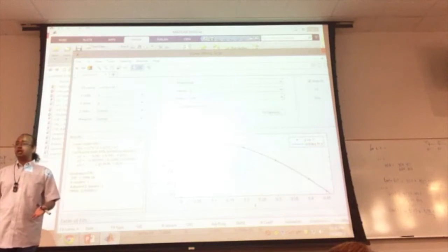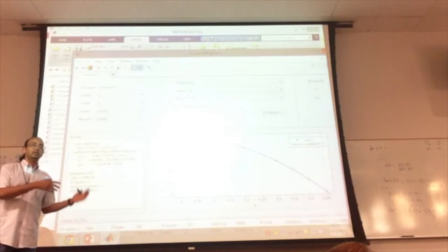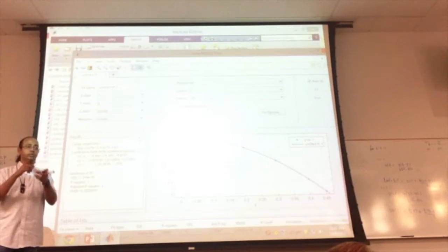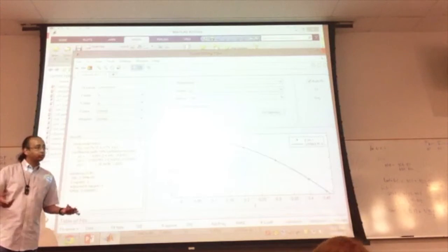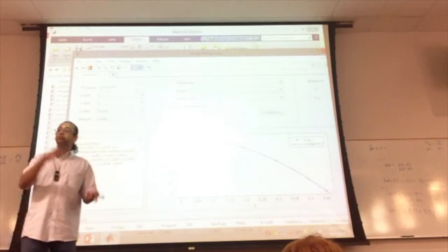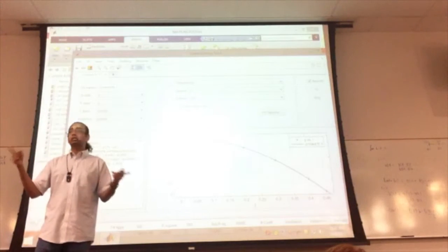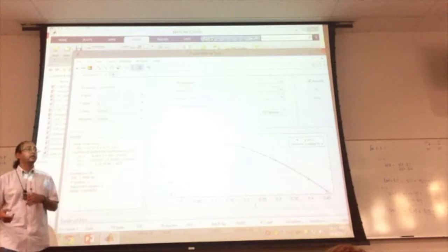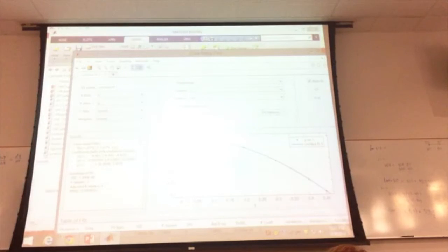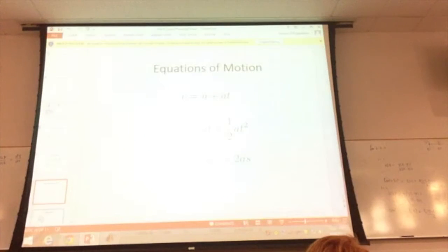You're going to use the data and calculate position, velocity, acceleration by simply taking the difference between 2 discrete points. And you're also going to learn to use MATLAB to curve fit, find the continuous equivalent of those discrete data points, differentiate that, and find out the velocity upon impact. All right, let's go to the next problem.